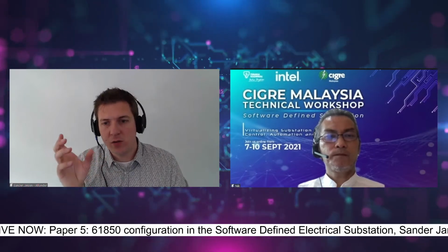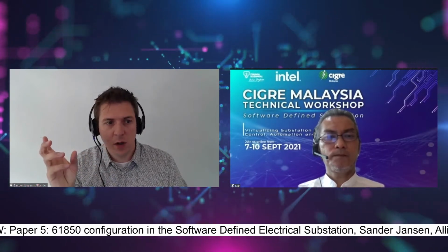Yeah, everything you can configure in 61850 SCL. If you talk about the actual protection algorithms, etc., I think that has more place in the CPAS project. And yeah, what we find very important is an open ecosystem, so that it also integrates with third-party devices, also currently proprietary or third-party algorithms. But if you look at the market today, most of the devices can be configured using 61850 some way.